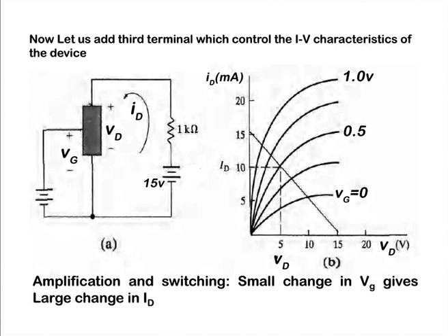If you have not applied any voltage on the third terminal, this one is the gate, then we will get the same IV characteristic similar to the 2-terminal device. Now, if you apply a voltage on this one, this voltage will affect the carrier flow between these 2 terminals. So, this current we can increase or decrease, depending on how much voltage we are applying and what is the polarity. So, this is the basic principle of field effect transistor. In a field effect transistor we are tuning the output current by applying some voltage on the third terminal.